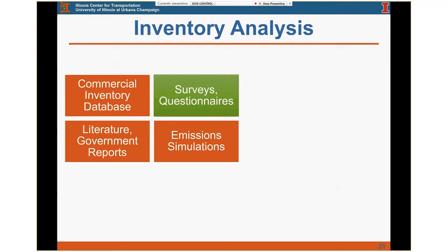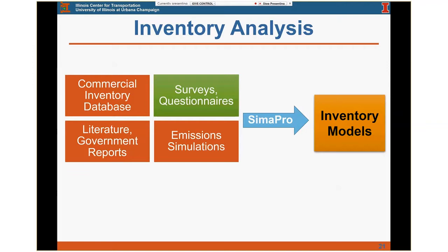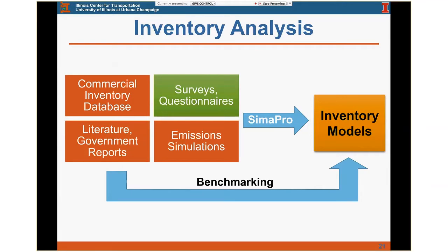And then we, of course, perform some simulations using these commercial databases and this LCA software. This LCA software is called SimaPro. There are multiple other programs available in the market, but we typically use SimaPro because of its user friendliness and also availability for academic settings. And at the end, we get our inventory models. Inventory models are those really required to, let's say, calculate the impact of asphalt mixture production, binder, aggregates, and everything that's being used in the production of pavements. And at the end, we perform benchmarking with some available data to make sure that our results are making sense.